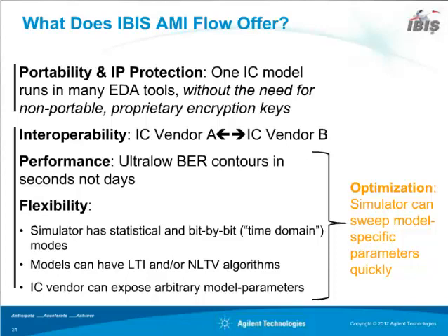One of the other benefits, because we're working at channel simulation, is that we can get to really low BER contours, and we'll talk about specifically how that's done in a while. And the last one really is flexibility. One of the things to really get to here is, yes, you can do sweeping of model-specific parameters and channel parameters, and that allows you to really interact with that choice between DSP function and channel to understand your DSP, your emphasis, your EQ, and look at CDR functionality in the context of a real high-fidelity analog channel model.